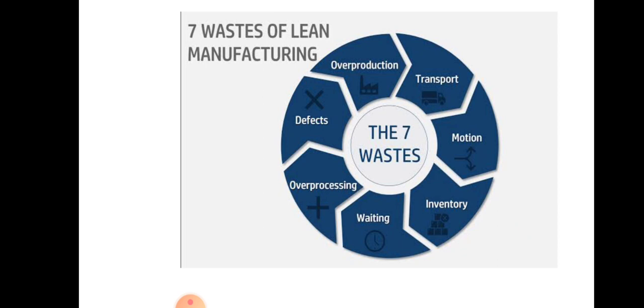It can also trigger other waste such as waiting or motion, and impact overhead cost, such as higher fuel and energy cost, or higher overhead labor in the form of lift drivers, as well as adding wear and tear on the equipment, right? It may also result from poorly designed processes, or processes that have not been changed or updated whenever required. So value stream mapping and partial or full changes in the factory layout may reduce the transportation waste.